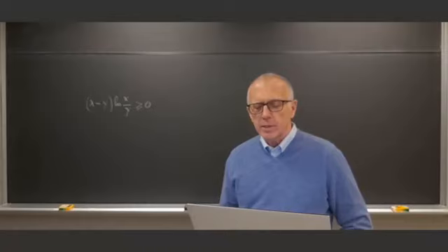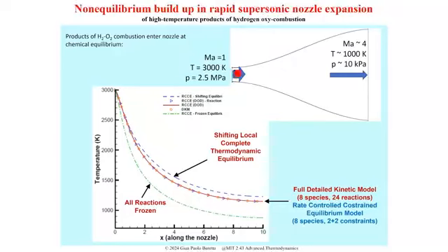combined with thermodynamics. But in any case, you have Mach 1, and then as a result of the expansion here, if you have a well-designed nozzle, the fluid will accelerate and become supersonic. For example, here it would exit at Mach 4. Of course, that means that the thermal energy gets transformed into kinetic energy. So the gas cools down, and also the pressure goes down.